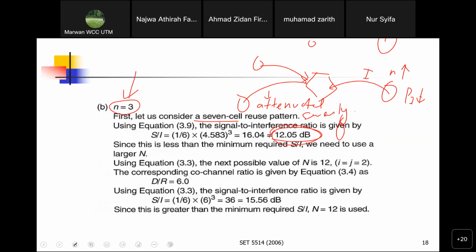It means that the interference starts to disturb you because the environment is better. Interference can propagate from far away to you without being attenuated severely. So a path loss exponent is actually a friend. It is going to help your interference limited signal if the environment is becoming more complex.